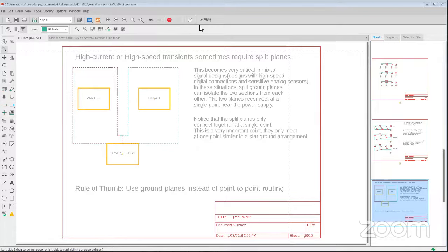But you'll notice that most linear regulators are set up to have a good rejection ratio at line frequencies, so at 60 hertz, 60 to like 120, 150, you have really good power supply rejection. But any frequencies higher than that basically come through. So any noise that your switching regulator has, and I don't know the exact frequency you're running your buck regulator at, but I'm assuming it's 100K and up, pretty much just gets through your LDO.